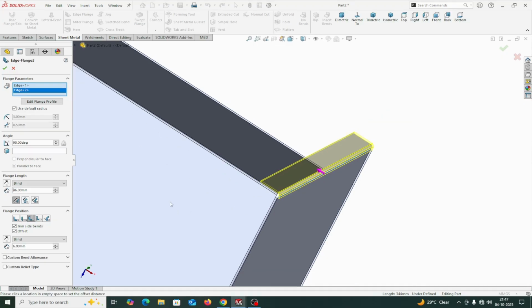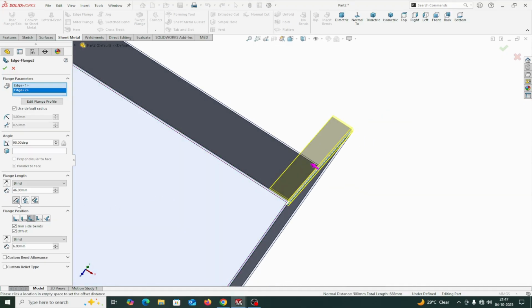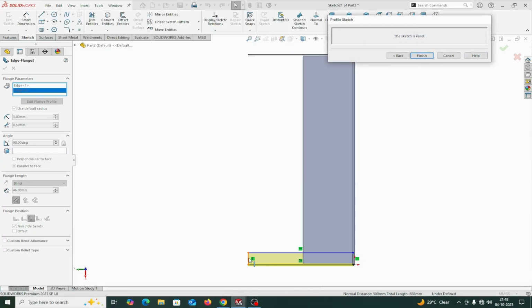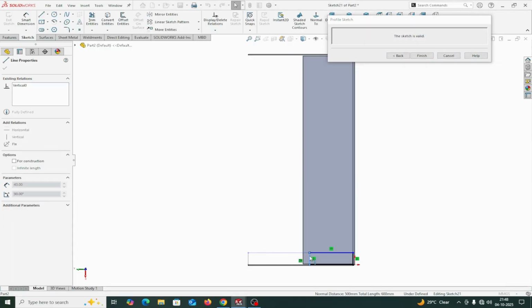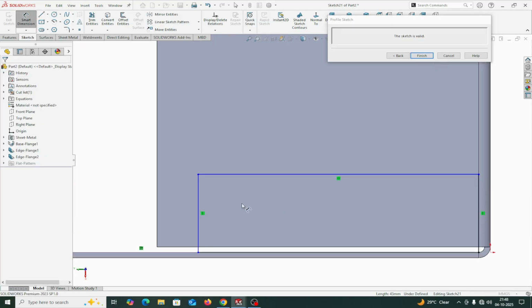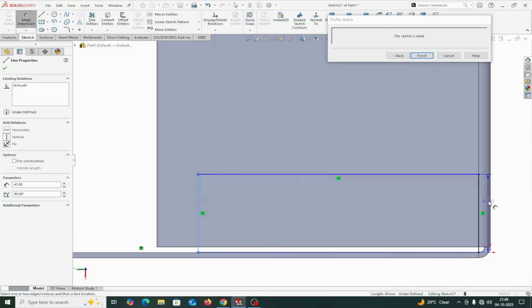This one. This is the outer virtual sharp. The flange height will be measured from the outer virtual sharp, and the bend will be outside, but there will be no offset in this case. If you take the second added flange, the height of the flange is, with smart dimension, equal to 165 mm.